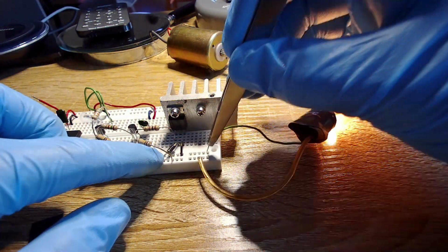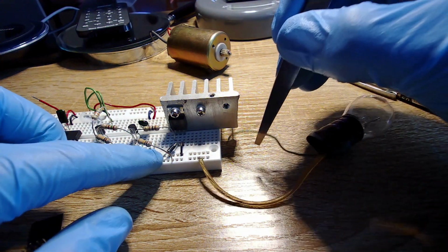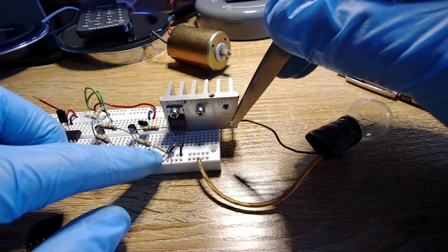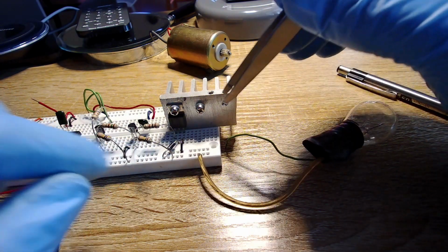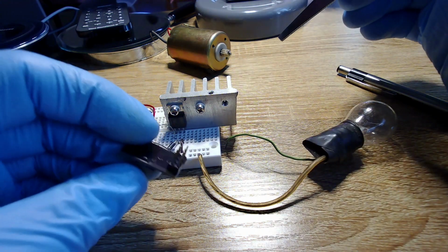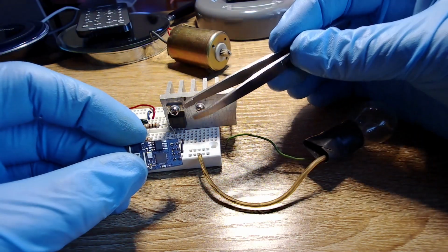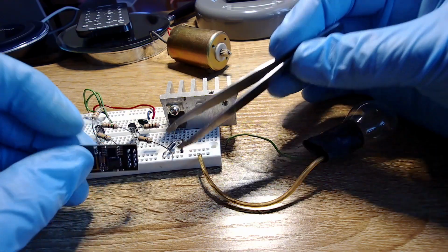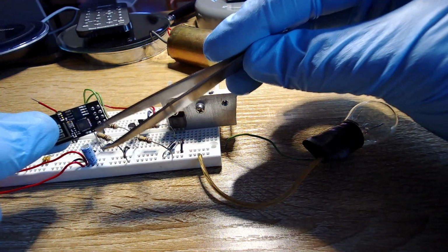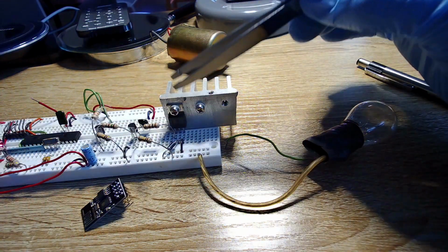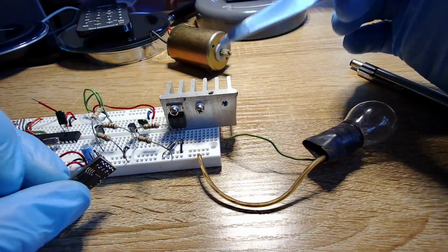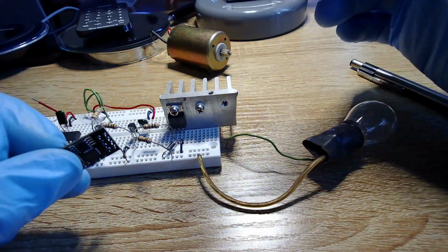But the interesting thing about the common emitter is that you leave the power, and the act of switching is at the ground. And the reason it's at the ground is, remember we mentioned before that the only thing common to these two guys, or whatever they are, is the ground. So what we can do is we can tell, something smart can tell something dumb, hey, just ground this thing. It doesn't have to go up to 13, or could be 30 volts, could be even higher.